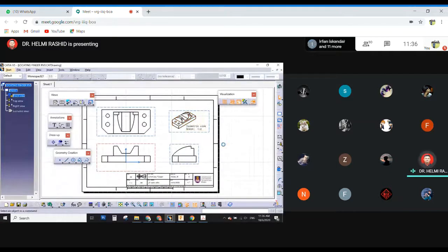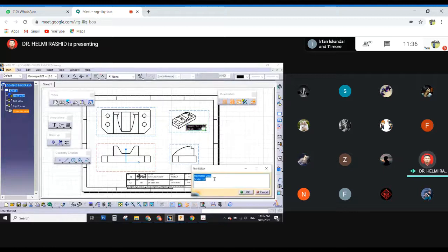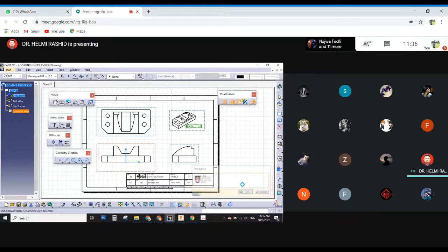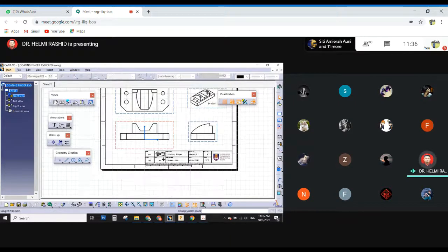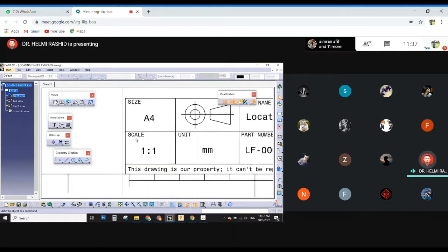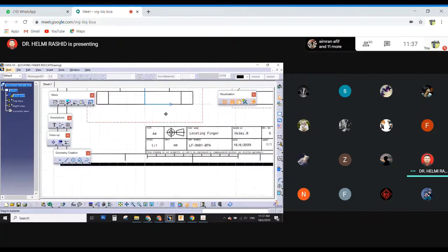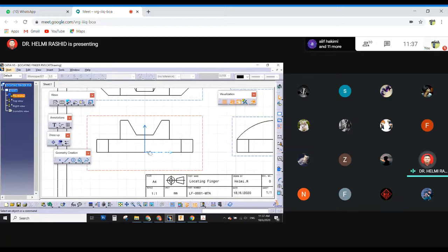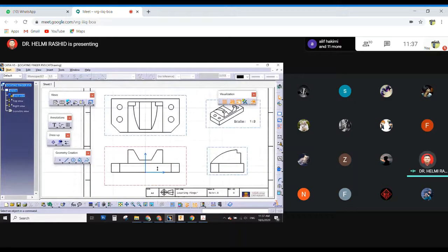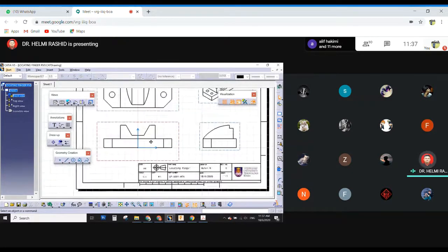Okay, so you know that this is isometric. Do we need to label it as isometric? You don't need to label it anymore, so you can just delete this. But how about the scale? About the scale, yes, you need to put the scale as 1/2, because why? In the drawing, when people read your drawing, a 1:1 scale means that those projections that you don't label, with any scales, they will understand that this is 1:1 scale.